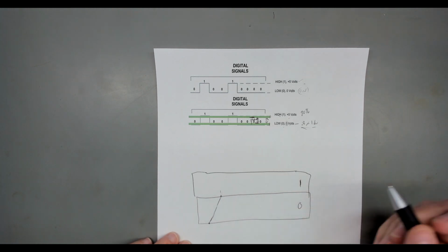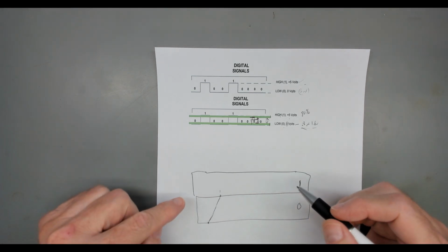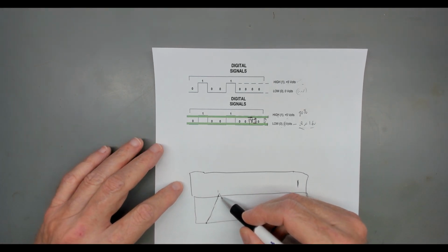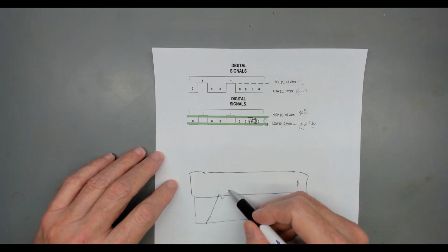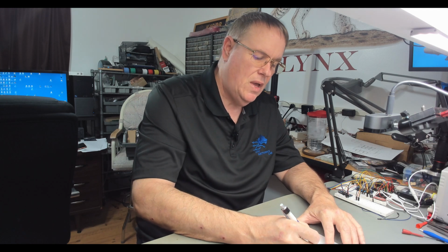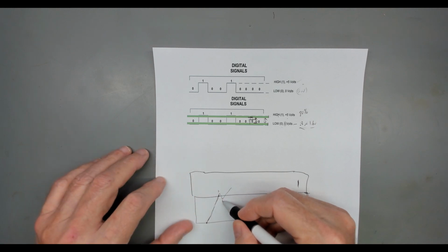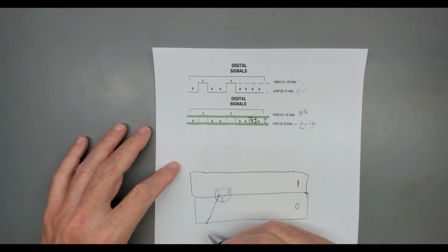When it does, transistors are going to come on. When transistors come on and current starts flowing, sometimes your voltage sags a little. So it's very easy to break into 1 and then immediately drop below that threshold momentarily as things charge and then come back on in. The problem we have with digital circuits is if this happens, if it worked this way, you would have a 1 and immediately switch to a 0 and then immediately switch back to a 1. You have corrupted data now because you only really changed to a 1. So that would corrupt all of our data if it worked this way.